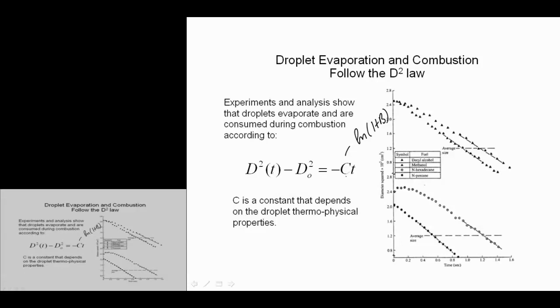And this law really just comes from the droplet mass conservation equation, where the realization is made that really it's just a recession rate equation, so we can just as easily write it as dr/dt times 4 pi r squared.